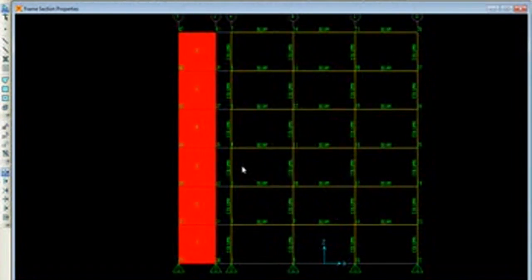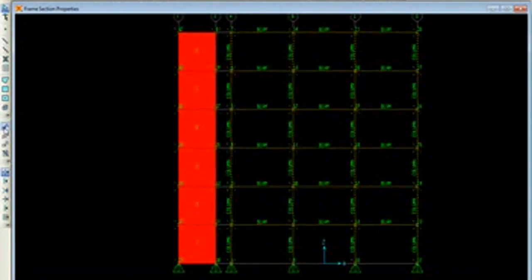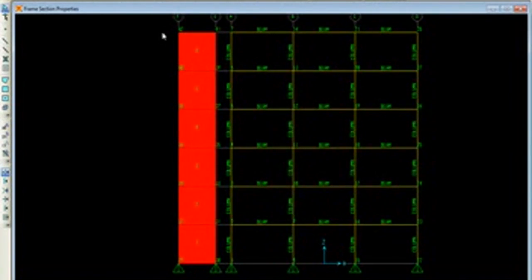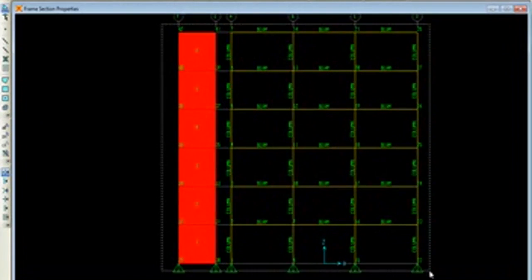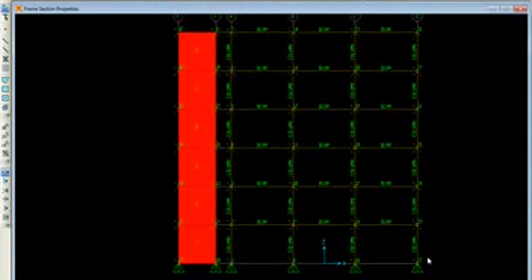Now the beam members have been selected, and now what we'll try to do is add joints to the members. So I will select all the members by windowing, or by selecting all. Now all the members have been selected. If you observe one drawback here, I want to give constraints to the member, but constraints will be given only at the joints. But now all the members have been selected, so please don't go for the all command right now. So clear all. Now I'll try to just window this, so only the joints will get selected.